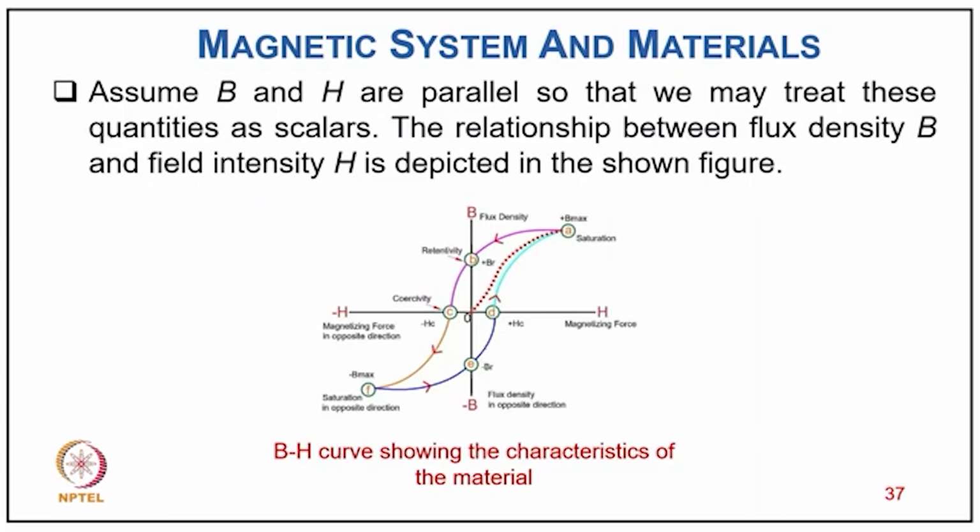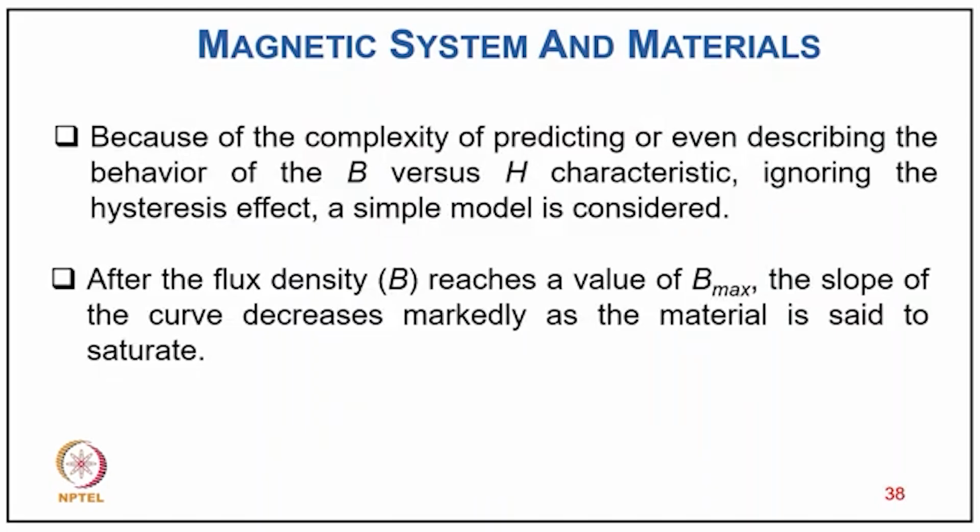However, typically for defining a soft magnetic material, we consider that this loop size, this BH curve, should be as small as possible, so that core losses are reduced. But when you are using a hard material as a permanent magnet, we don't expect it to go through alternating flux. So we want this area to be as large as possible, so that the energy density provided is quite large.